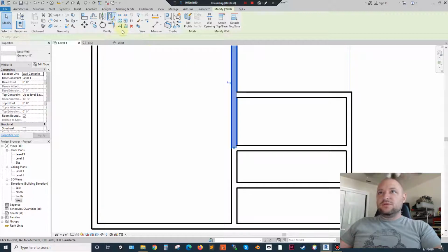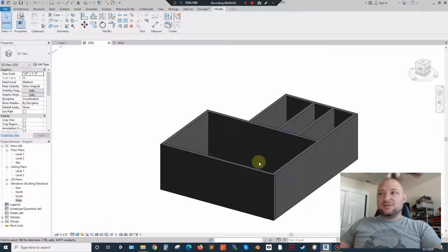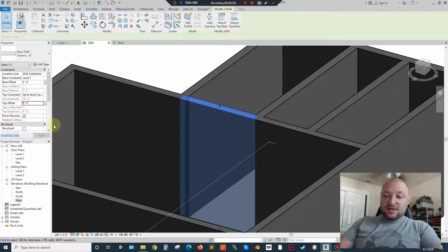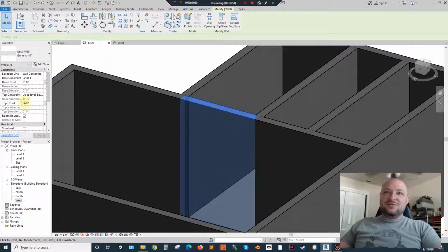So oftentimes we'll have to go in there and make modifications to things. So for example, if I wanted, say, a raised ceiling in this part of this house, I would actually have to separate these chunks out. And so here's a case where you'd want to use a top offset. Oh, shoot. Keep the mouse in the box. There we go. And 2 foot.